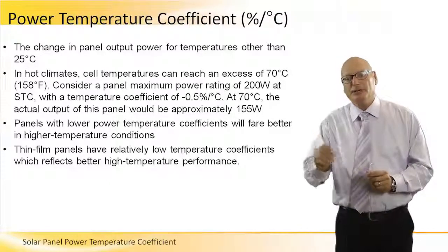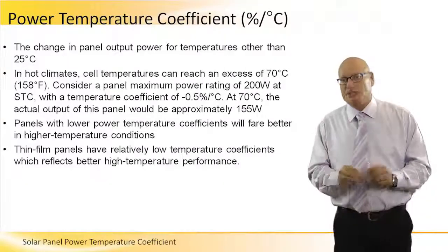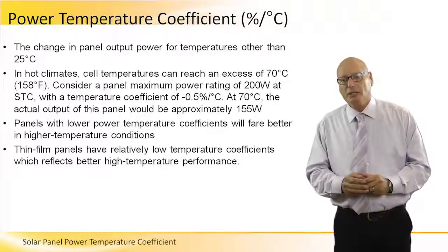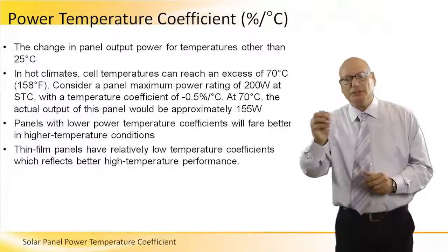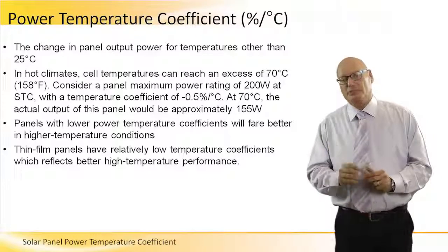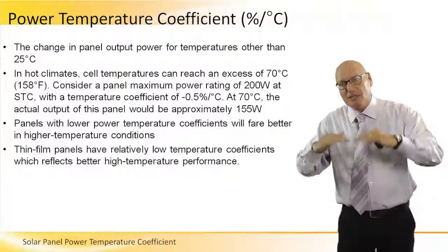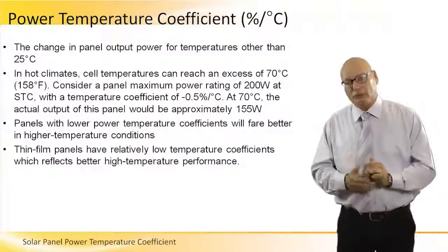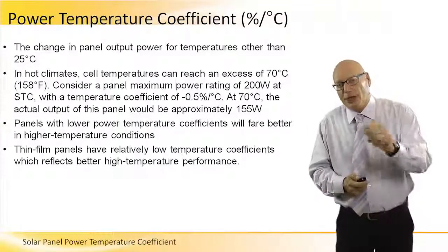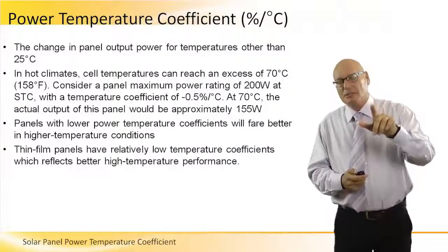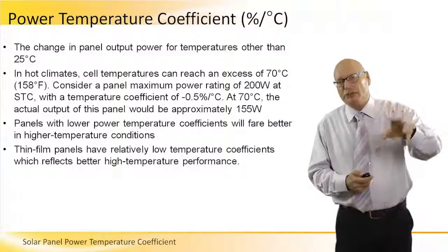Thin film panels have relatively low temperature coefficients, which makes them better and reflects in better performance in high temperature areas. However, their total efficiency level is lower, as we've seen before. So in very hot places, sometimes it's preferred to use thin film technology.